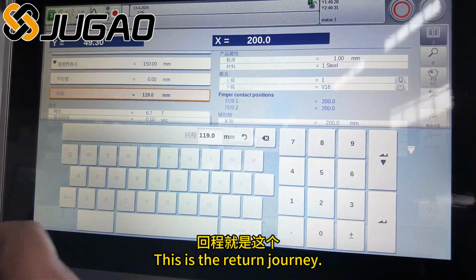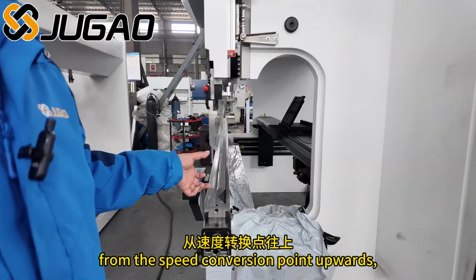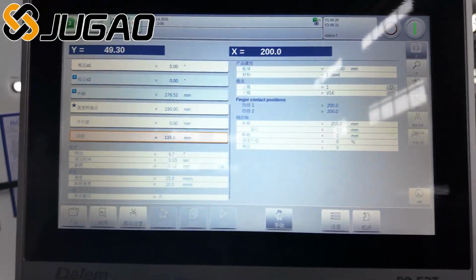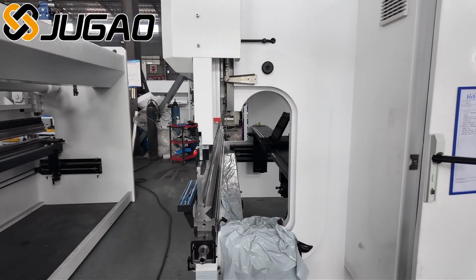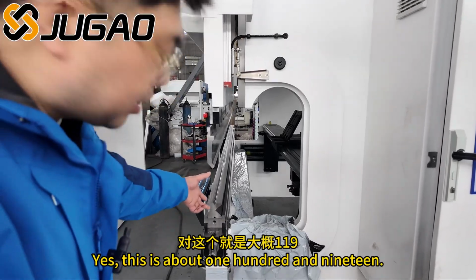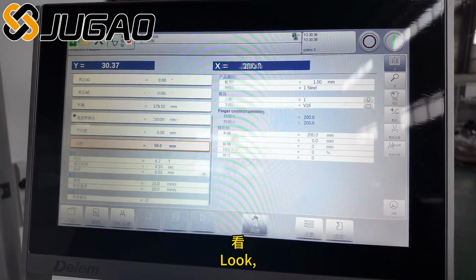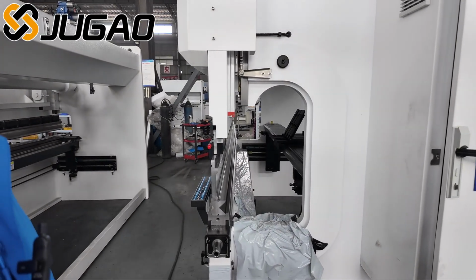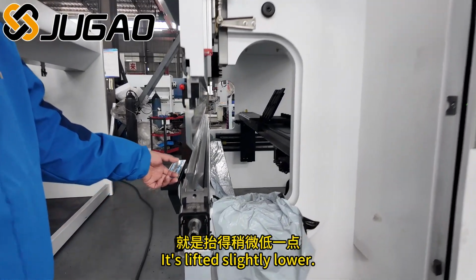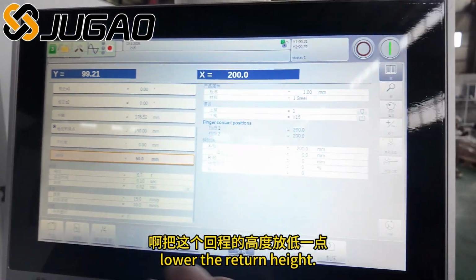This is the return journey. Lift the knife to a height from the speed conversion point upwards. For example, I'm at 119 now. I'll lift it up to see the effect. Yes, this is about 119. I'll set 50. Look, it's lifted slightly lower. Some customers want to improve work efficiency. We can lower the speed and lower the return height.